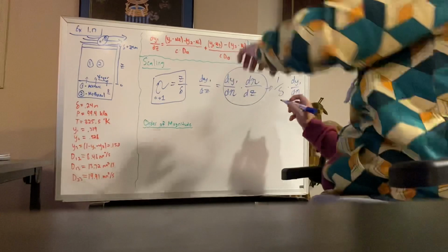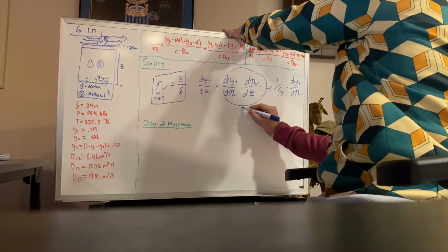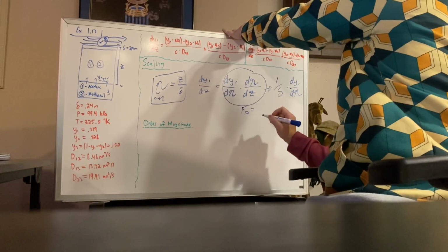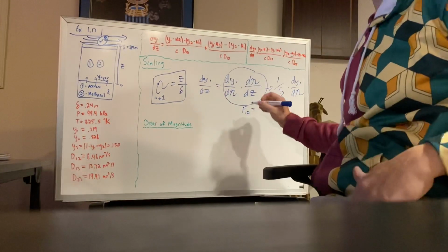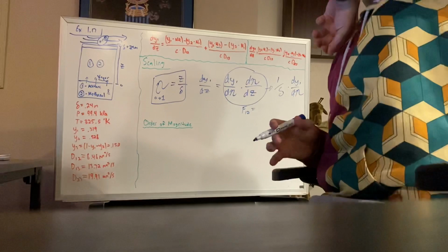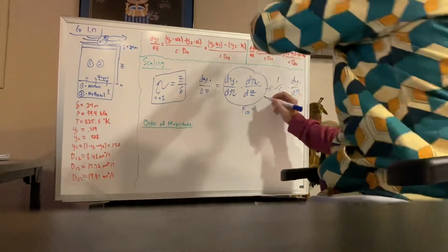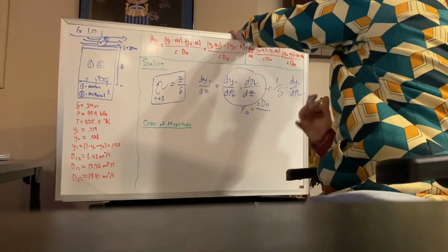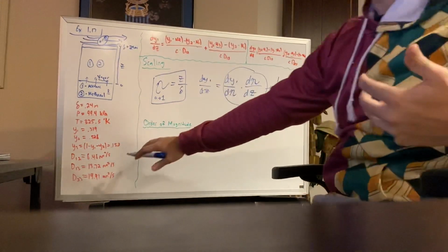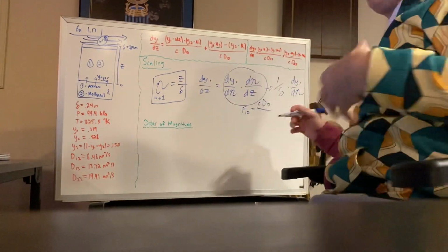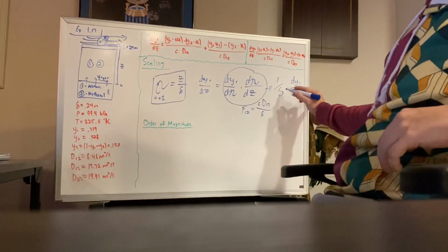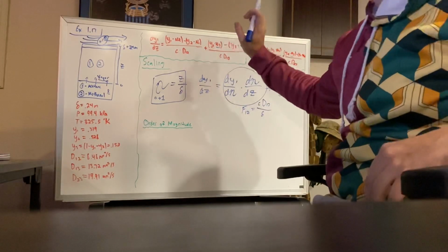But I'll go ahead and take care of that, because by doing this, what we will do is set a new equation, F12, and this will be equal to the concentration multiplied by D12, which is the diffusive constant given between the two components, and then over the length delta, which will account for that delta that we see here if we were to input this directly into the equation.